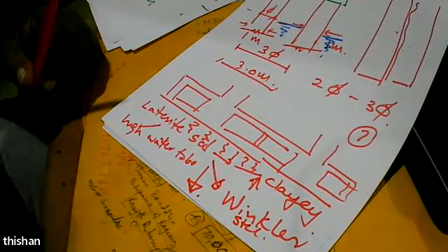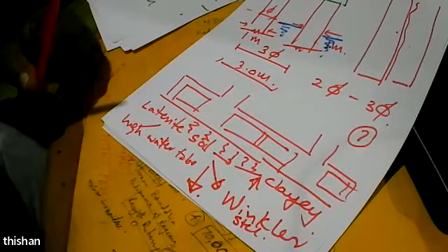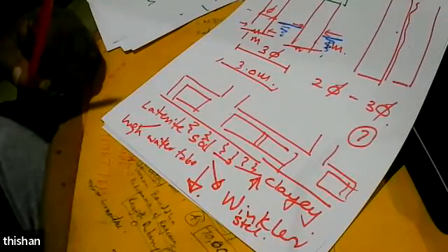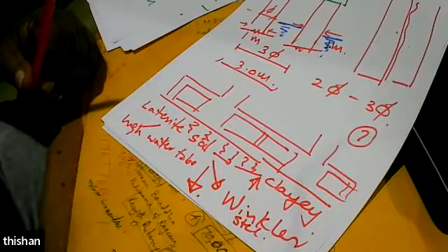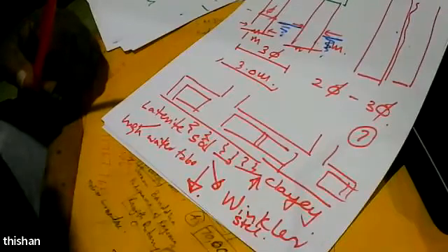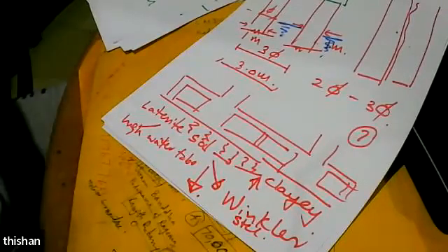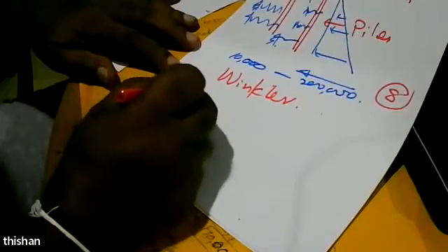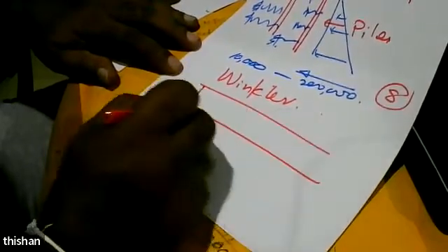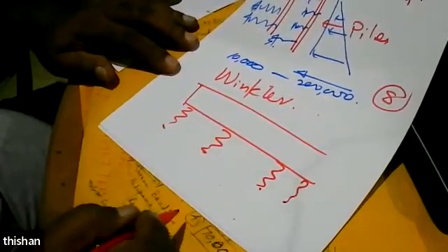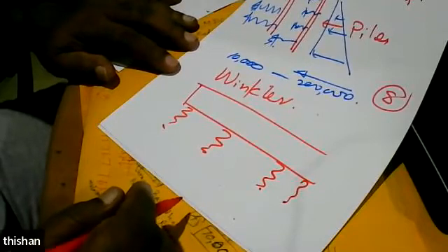And if most of the structure is going to be buried in good quality sand, you might consider. And if the water table is also lower, the good laterite soils having a lot of sand, then you model it as a set of springs like this. So you have, let's say, a rough foundation, a spring here, another spring here, spring here. And then model it. It's a very easy, straightforward task.